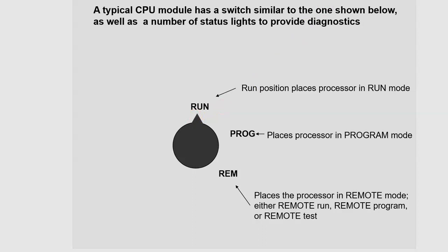Before any of that's done, though, a big difference between a PLC and a regular PC is that often the PLC will have actual memory in the programming device itself. For example, the PLC that I usually bring to class when we meet face to face has a programming device that has its own memory. So when I enter the program, I'm entering it into the programming device, not the PLC. In order to move the program from the programming device to the actual CPU or PLC, I have to download the program. There's a button that says enter on the device I have, and on your simulation software it says download.